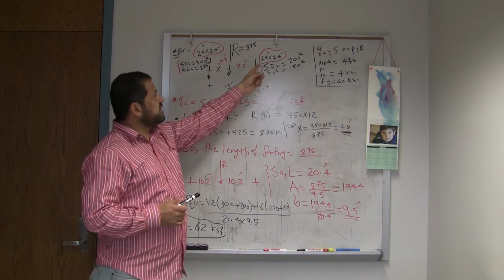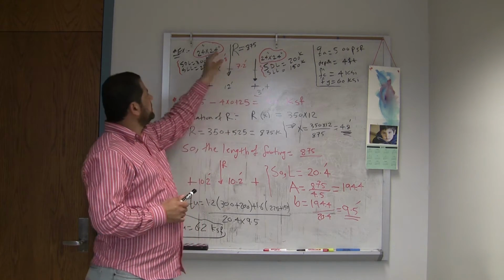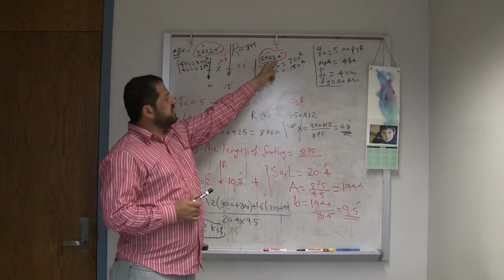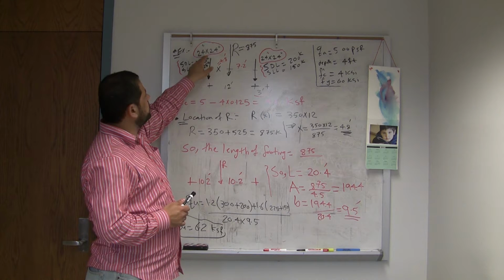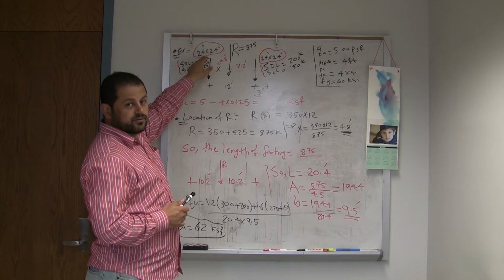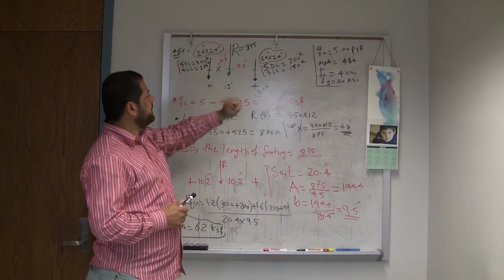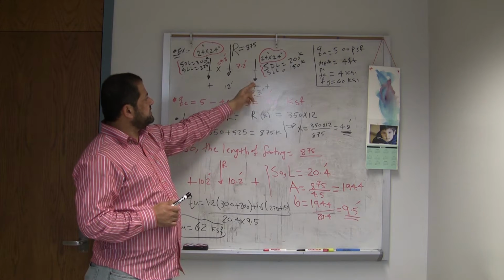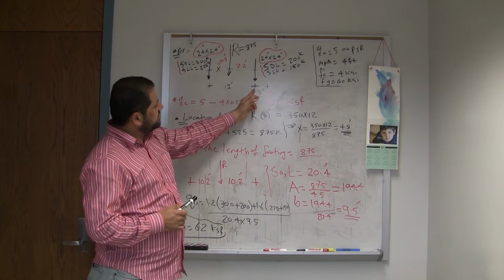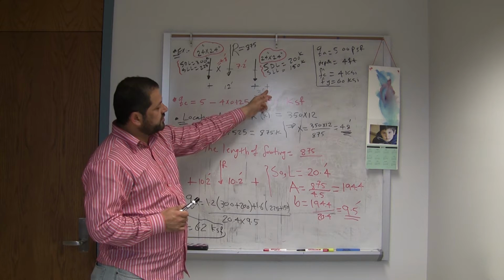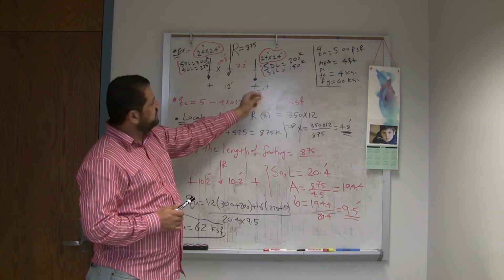So this column is 24 inch by 24 inch, which is 2 foot square. And the interior one is also 2 foot by 2 foot. It's a square column. The distance between them, center to center, is 12 foot. Again, the distance from the center of this exterior column to the border line is 3 foot.